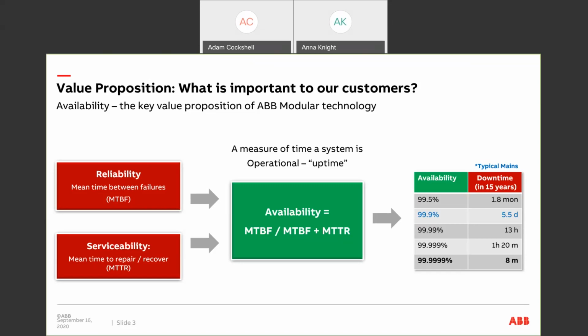This really shows the availability of our unit and how this can really assist in applications such as an oil and mining venture, where you may be a considerable distance from your local township or your local service department. The requirement to, one, have redundancy built into the UPS, and two, be able to repair or substitute a power module out relatively quickly and with relative ease is something that our customers are really seeing the benefit of from this particular UPS.